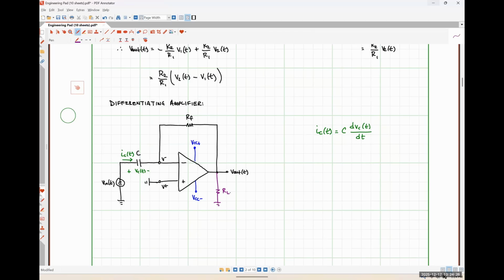So we're going to do basically the same analysis that we've done in every other one of these circuits, but we might have to make some very, very slight changes, okay? So first, I'm going to, again, observe no current can flow into or out of our input terminals. By inspection, we can see that the voltage present at our non-inverting input terminal is 0. And this will be the voltage present at our inverting input terminal as well. So I'm just writing that down here.